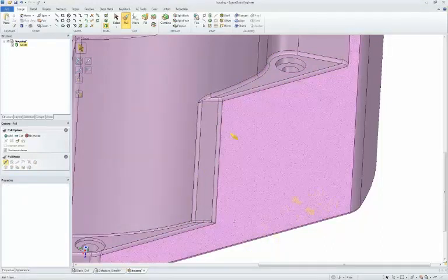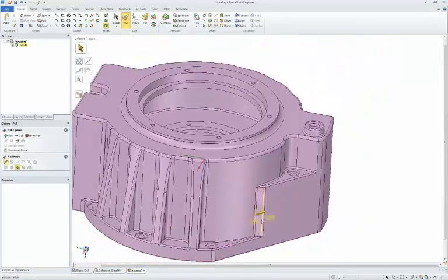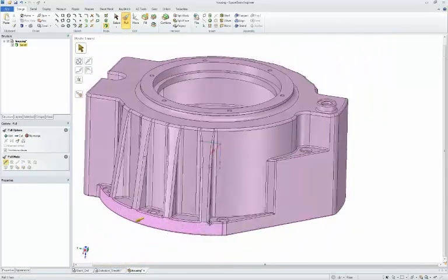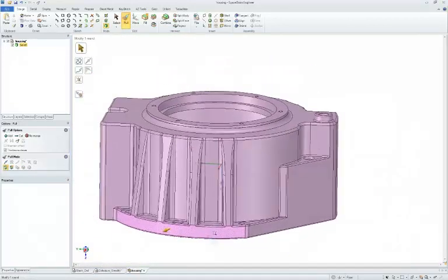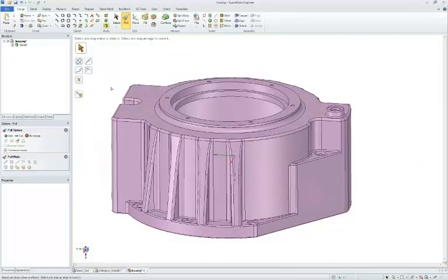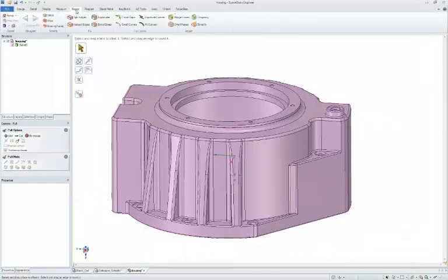But now we've eliminated that small sliver face, which really could be a pain when meshing. But that's the key thing that this lets you do, is it lets you work with incoming geometry, again, any way you want. Let's look at a few other things with small faces.